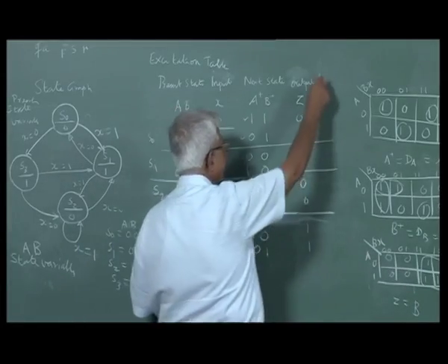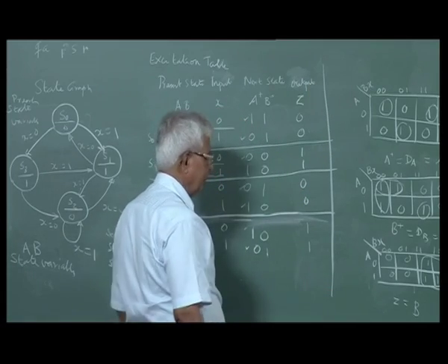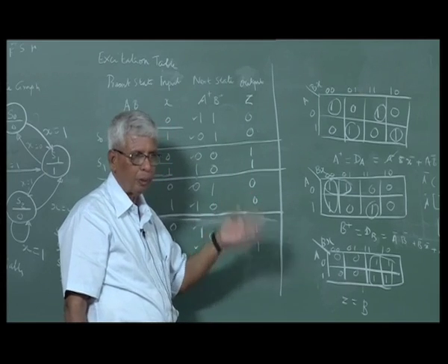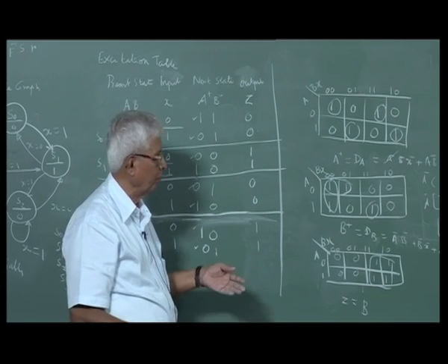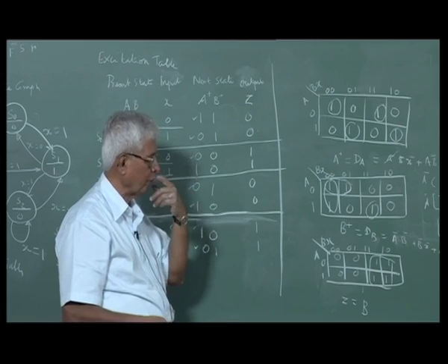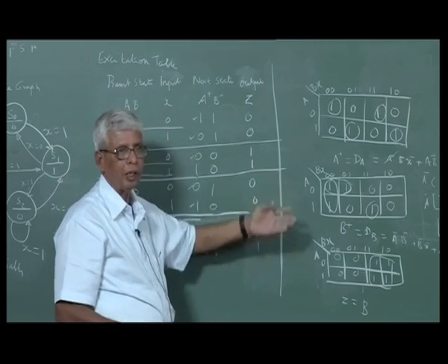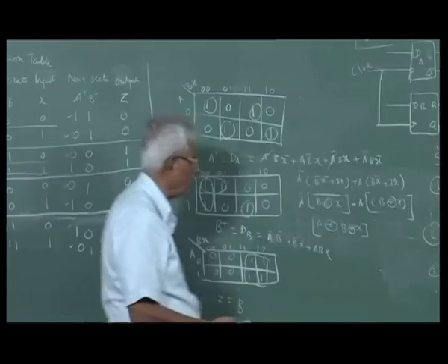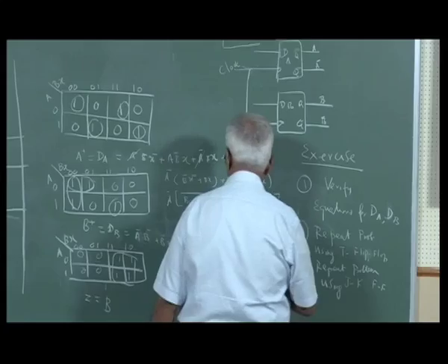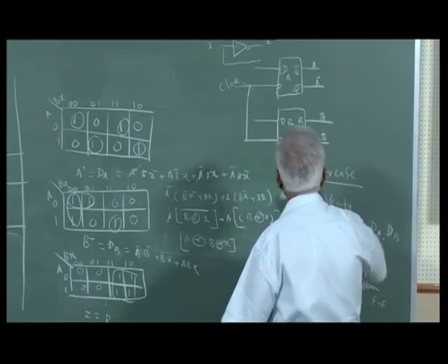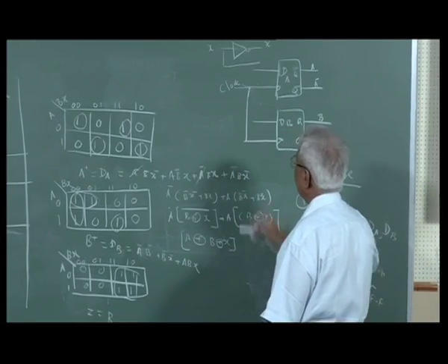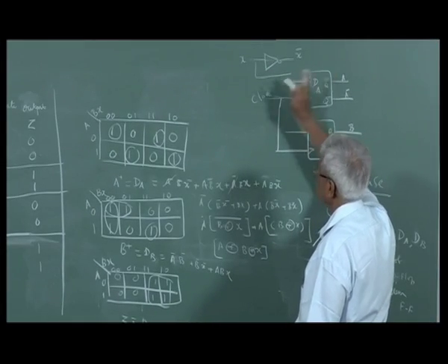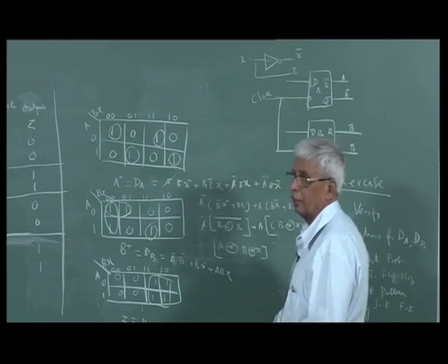Up to this is the design consideration. Actually this is the design. This is mundane work. After doing the design, you implement using D flip-flop, JK flip-flop, T flip-flop. You have to draw the corresponding Karnaugh maps and simplify the equations. All the variables are available here. You don't have to generate them. A, B, A bar, B bar are available; X is input, and you may have to generate X bar. That is all you need to do, one extra inverter.